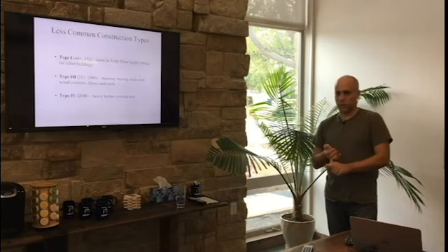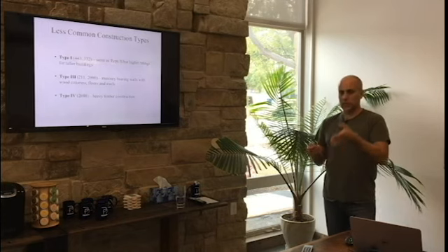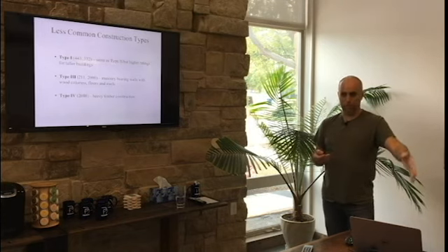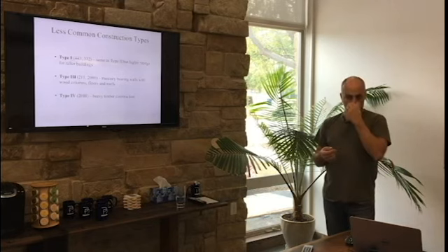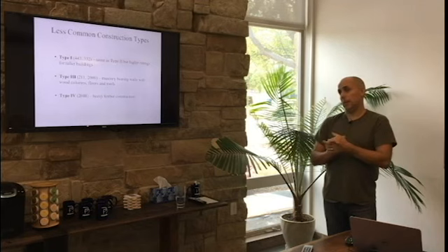We can do heavy timber trusses inside the building, etc. I still have to meet flame spread requirements inside the building, but you can mix heavy timber into type 5 construction. You can also mix it into type 2. I have to go back and double check that, but I think you can also mix it into type 2. I might be wrong on that one.